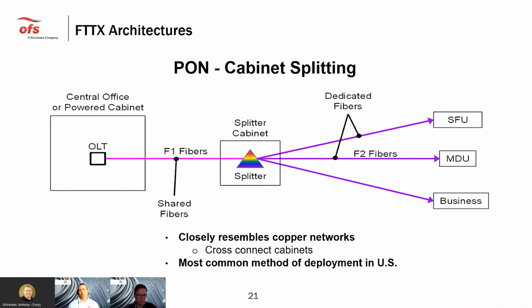And what this also does is strike a balance from a cost perspective, to where the cost of the F2 or the outside plant network, specifically the splicing, and then you also have slightly smaller cable sizes, is going to go in tandem with the cost of the electronics. And so you've got this nice balance going on of cost associated with the outside plant network, and then cost with your electronics.